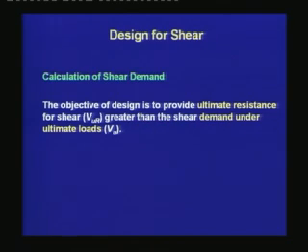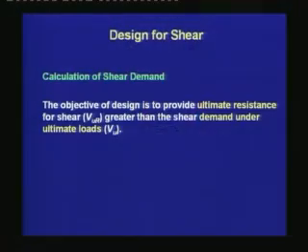First, general comments. The objective of design is to provide ultimate resistance for shear, which we shall denote as VUR, greater than the selected shear demand under the ultimate loads, which we shall denote as VU. Thus, first we need to know the shear demand VU.